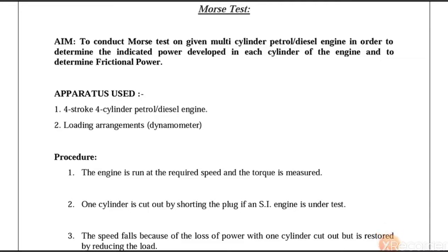Hello everyone. Now we are seeing an experiment called Morse test. The aim of this experiment is to conduct Morse test on given multi-cylinder petrol or diesel engine in order to determine the indicated power developed in each cylinder of the engine and to determine the frictional power.